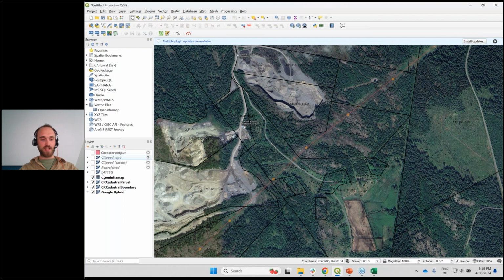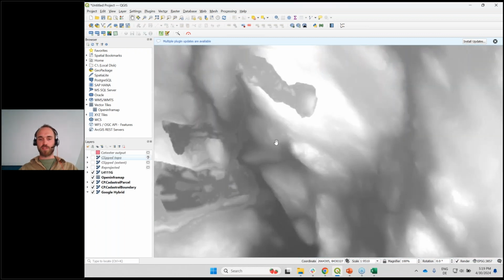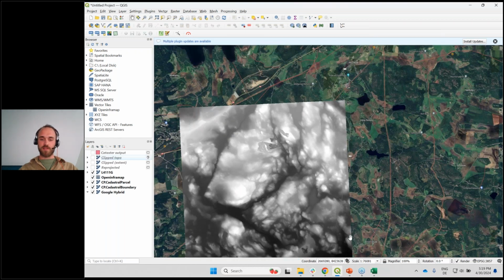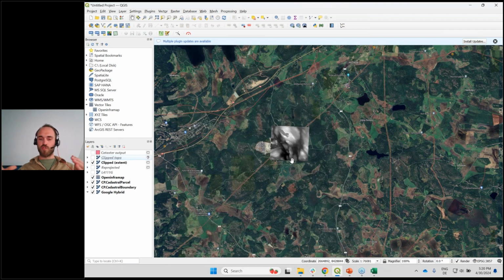So what I did, and I prepared this already for today, first things first, I uploaded the raster file. If I zoom out, I see that it is that block we saw earlier. And then I had to do a few steps. These steps are described in an article we will also share with all the attendees. Basically, the steps are reprojection, so you have to first project it to the right coordinate reference system. Then you have to clip it. So if I clip it, that means I just have to shrink it down a little bit.